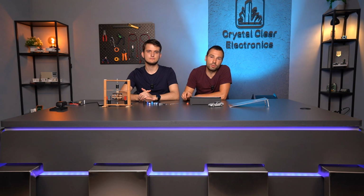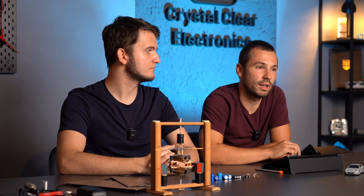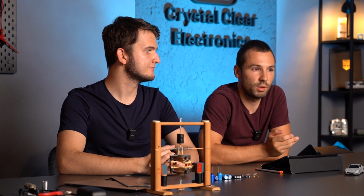I find it important to add that the terminals of the voltage source must not be short-circuited, connected with a low resistance wire, because then a very high current will flow due to its almost constant voltage, and this can lead to breaking the device and also to personal injury.